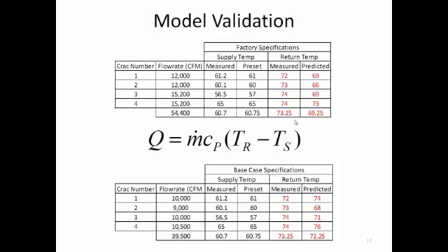And yes, there could be some mixing that's going on here that I'm not accounting for, Liz, such as there could be some bypass airflow through the tiles because I didn't turn on tile leakage. There could be cable cutouts I'm not aware of. There could be some underfloor obstructions I'm not aware of. But in this case, I didn't have a lot of data to go on because it was a remote situation, so the approach I took was to vary those flow rates a little bit. And you see here that the predicted and measured came in quite nicely. So I'm within a degree there on average. And that tells us that the physics, at least of the cooling systems, are running fairly well.